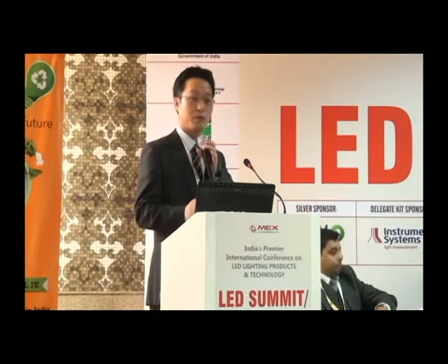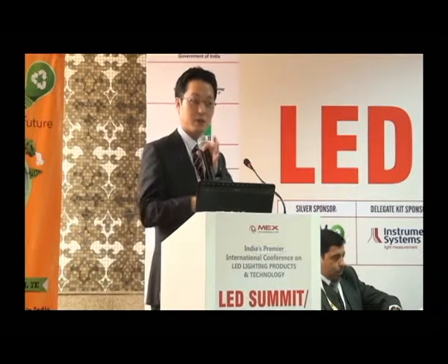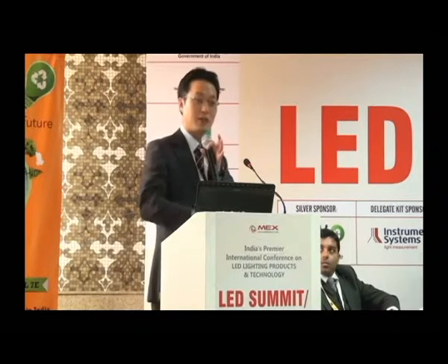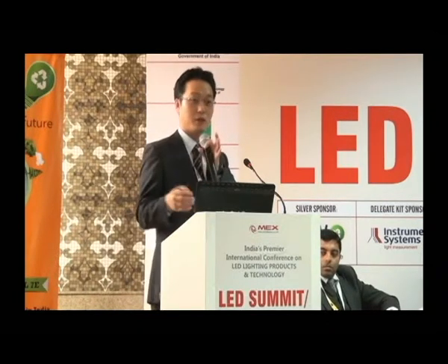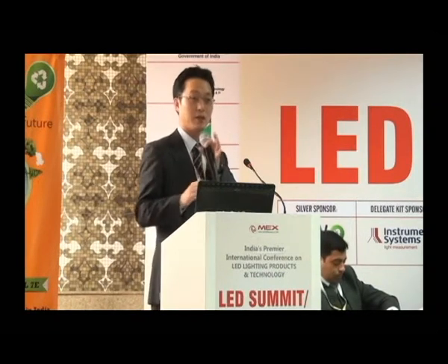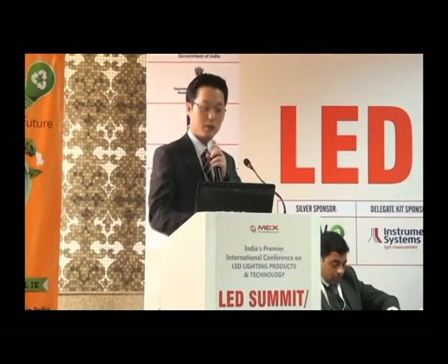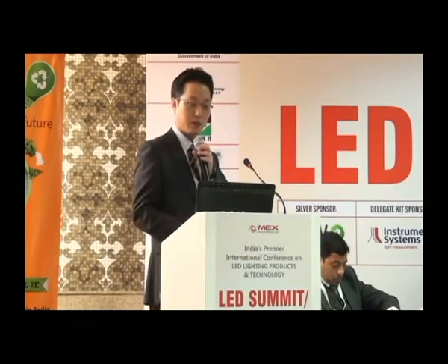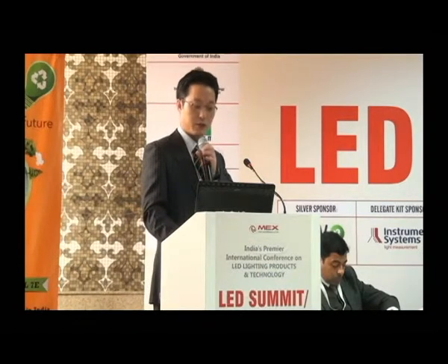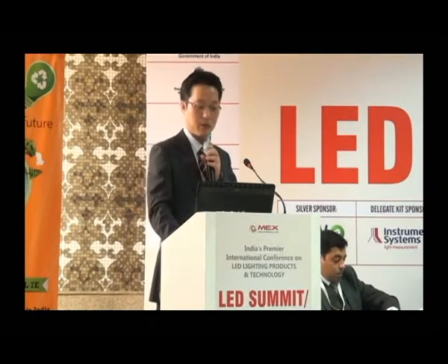And this grade is a little UV curing grade, so they do not need the molding process to make a dome-shaped LED lens. They just dispense and then cure. Normally, if you drop one water drop on the top of the glass, it makes a dome shape. After that, if you fix it with UV light, that dome shape will be maintained. After that, you do not need a mold process to make the lens. That is the reason why this grade was developed. So this is also commercialized and used for such non-molding process LED lens applications for lighting.